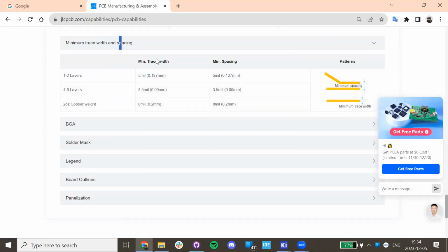So, minimum trace width. Here you can also see the spacing. We're doing 1 to 2 layers. Here they also give you an explanation. You see how this one is minimum trace width, 0.127.